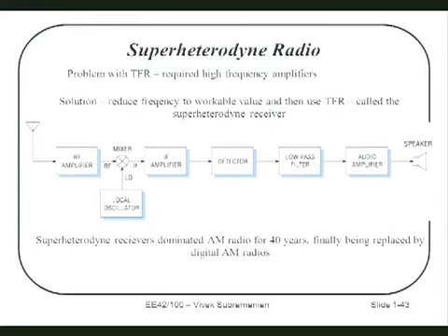Now, it turns out it's really difficult to design a filter that is tunable and precise. If I design a filter and it's really, really good at 740, but then I change its tuning to be at 710 or 860, it's never as precise. So that made it difficult to have a good quality radio that you could also vary the frequency of.